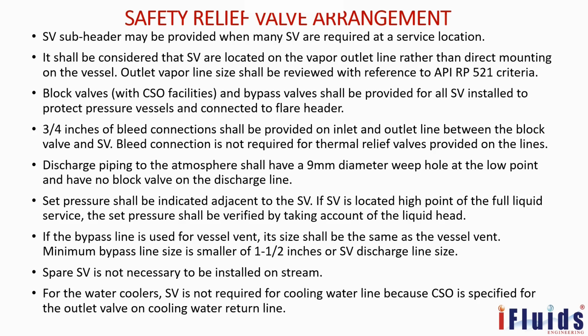Only one is enough. For the water cooler, SV is not required for the cooling water line because CSO is specified for the outlet valve on the cooling water return line. So the cooling water return line is always open. We never shut off the cooling water return line. That's why SV is not required.